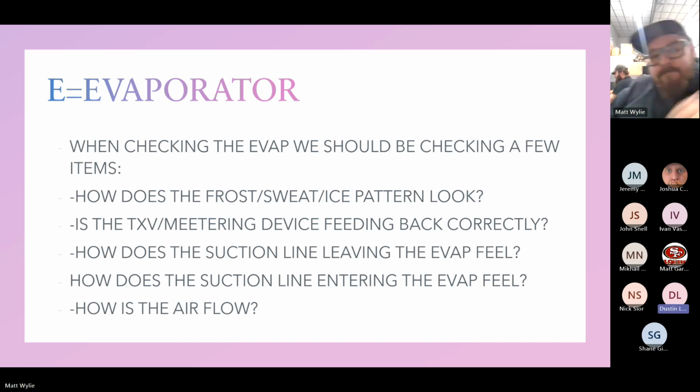I'll just say too, because of the fan blades, you figure that little bit of extra weight. That's why it's so important when doing PMs to pull the guards off and clean the fan blades. Don't just brush the coil, take it apart and clean it all so you have maximized airflow. You also lose life of your fan motor, because you put all that extra stress on it and the motor's going to die a whole lot sooner than it should.